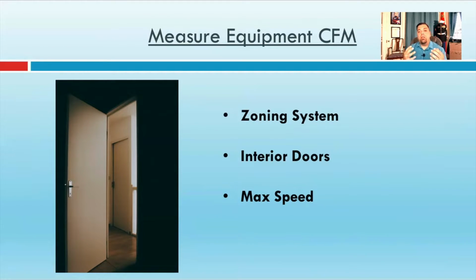So really, really important. Make sure that those doors are open and you have all of those return paths wide open. Now, if the system was not designed correctly and you did not have a return in every bedroom, you're going to see pressure differences and it's going to affect airflow. So you could have a higher return static pressure because you're pulling all of your air from a hallway, which obviously doesn't meet code, but they're out there. And if you're doing a retrofit, this could impact volume of air. So very important you test it both ways.